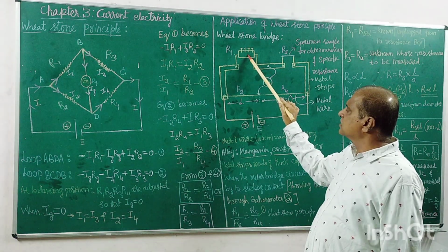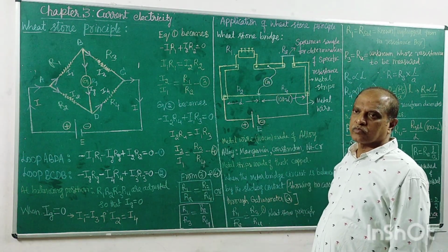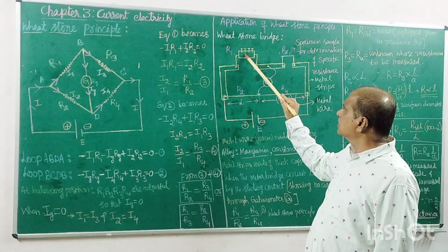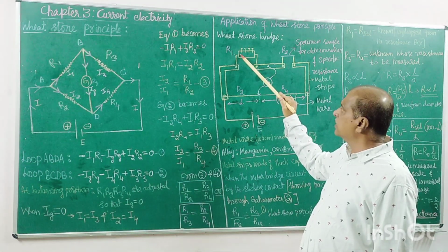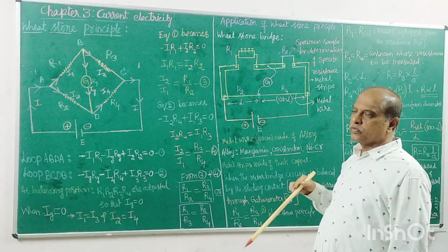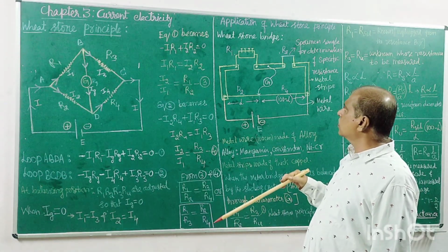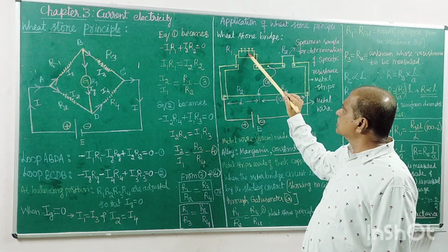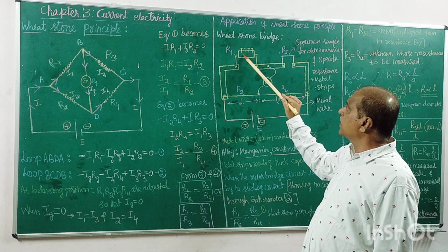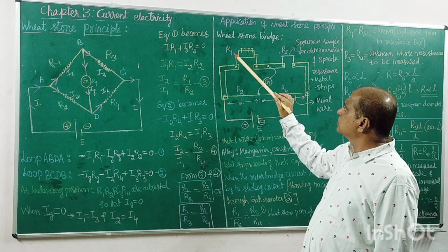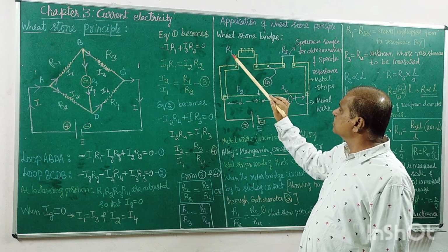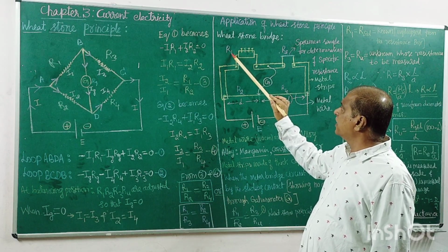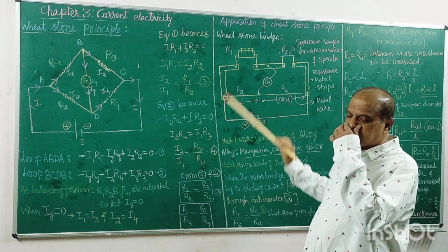It is called a resistance box, where there are a number of plugs and each plug has its own resistance. The plug can have 20 ohm, 30 ohm, 40 ohm, and so on. So these are resistance boxes with known resistance values. It is R1. When you unplug that, it is the resistance of that. R1 is the standard known resistance we can fix.